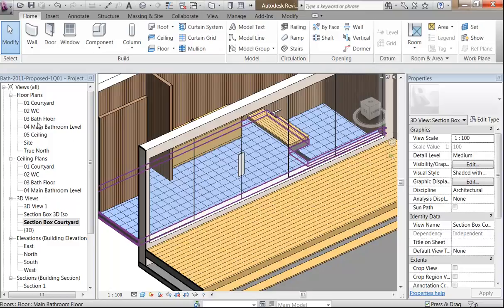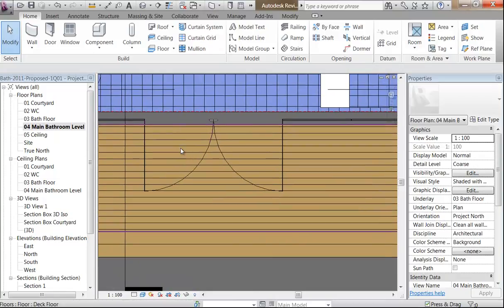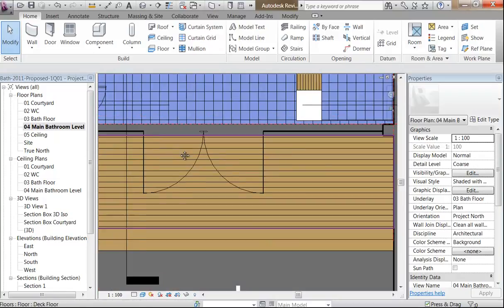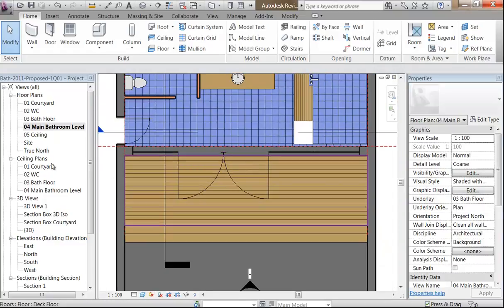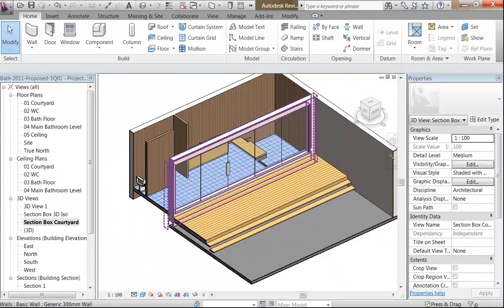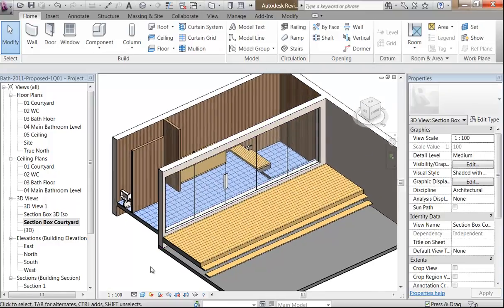You shouldn't really do double doors that way most of the time in a curtain wall. There are better ways, but in this case it works well just because I want my doors to be the same size as my other panels. So they're nice big doors, but that's okay. That's what I want here. Okay, so that's a simple way of putting a big opening into your main wall, rather than using windows. You could use windows to do something similar, but it'd be more work.